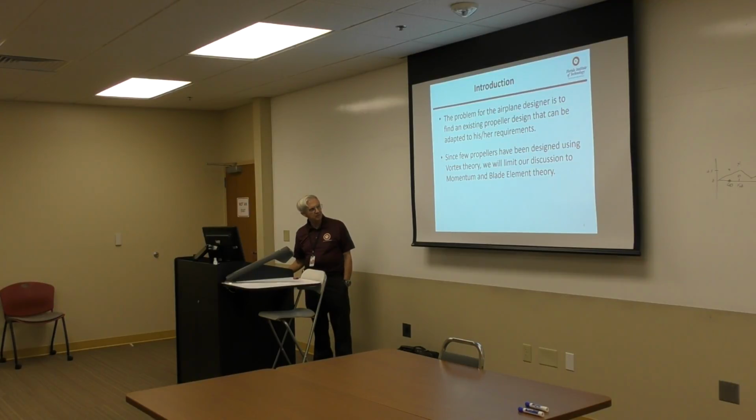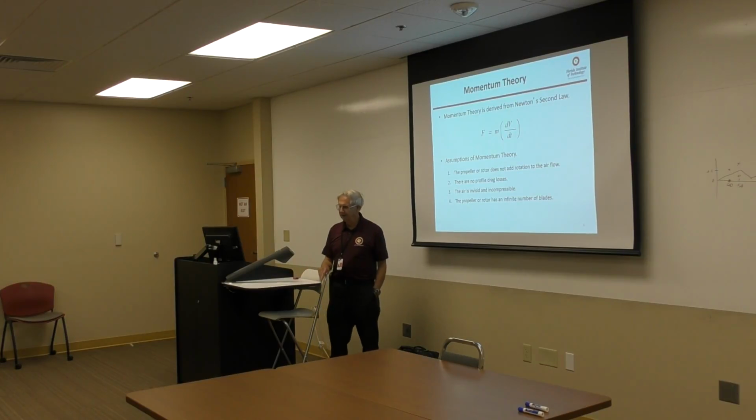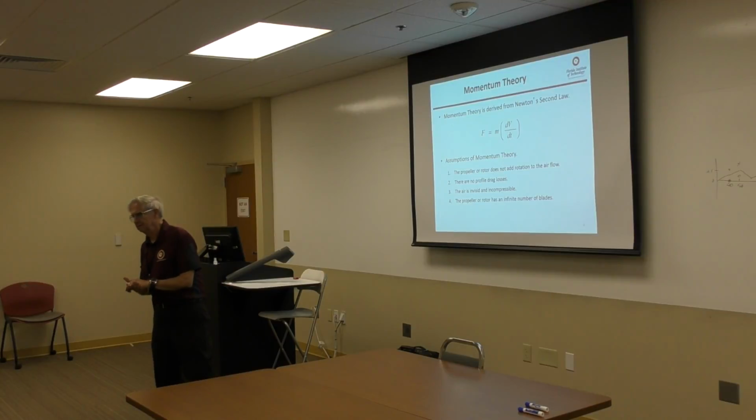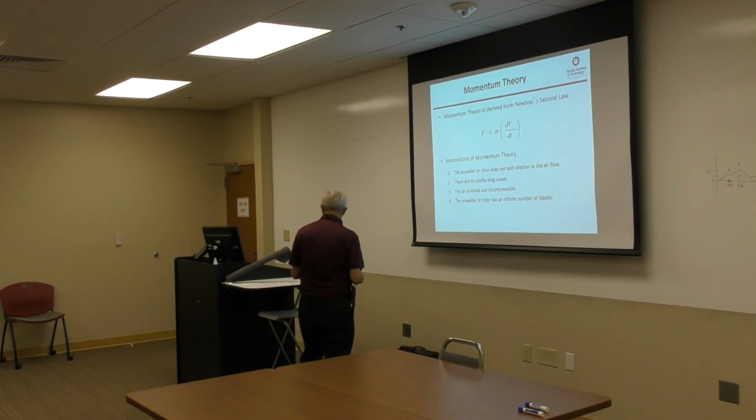Only recently has there been design using vortex theory. I know some of the companies now are starting to use that. But again, you can't, like a new airplane, design a new propeller every time you get a new requirement, just because of the cost of doing the design and certification work. So generally it doesn't happen that often.